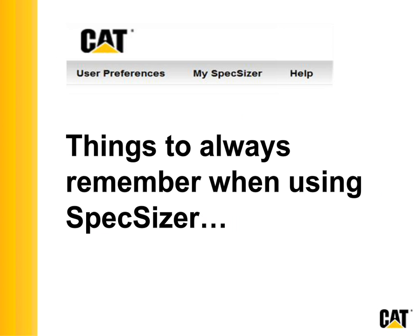The other thing is pay attention to how you sequence your loads. Remember we talked about the restrictive frequency dip and voltage dip? Let me just go over it one more time. If you sequence a load with restrictive frequency dip or voltage dip early in your load scenario, all successive loads will adopt that restrictive voltage dip and frequency dip, and you will oversize your genset. And avoid that. We talked about the optimizer. That's one thing that the optimizer does. It basically mitigates that circumstance.